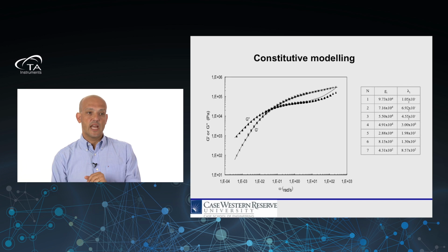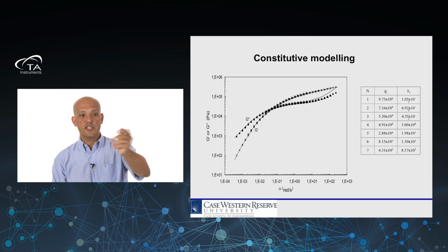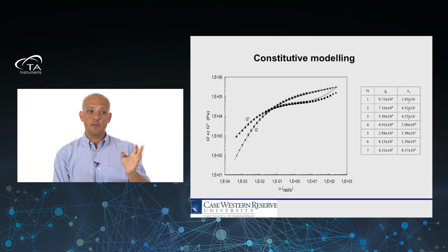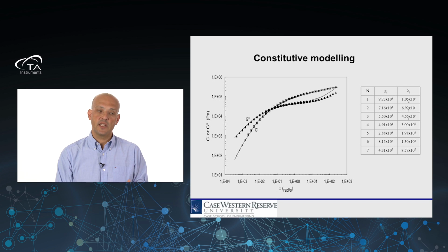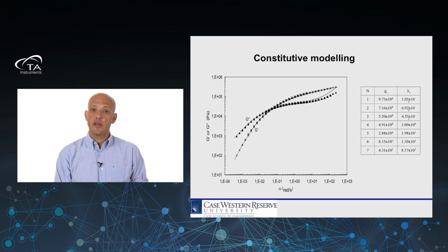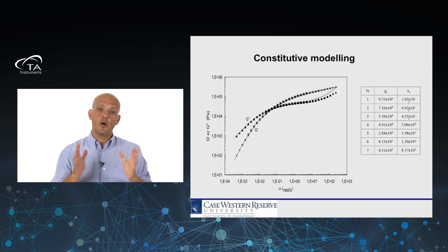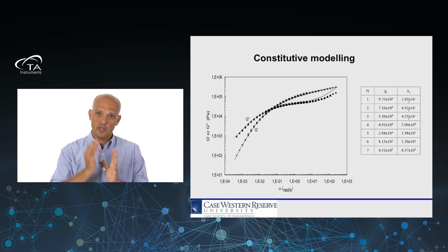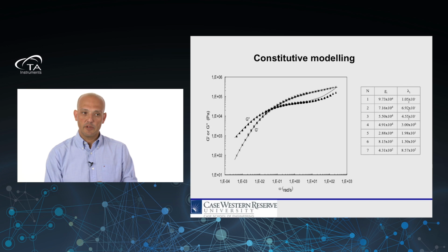So just to show you the kind of fit that we have, this is for the high impact polystyrene, G', G''. The symbols are the experimental data, the lines are the results of the fit. So a decent fit. So in principle, we can model quite accurately the linear viscoelastic behavior, the low deformation behavior, or the small deformation behavior. And we can do that with 7 relaxation times.